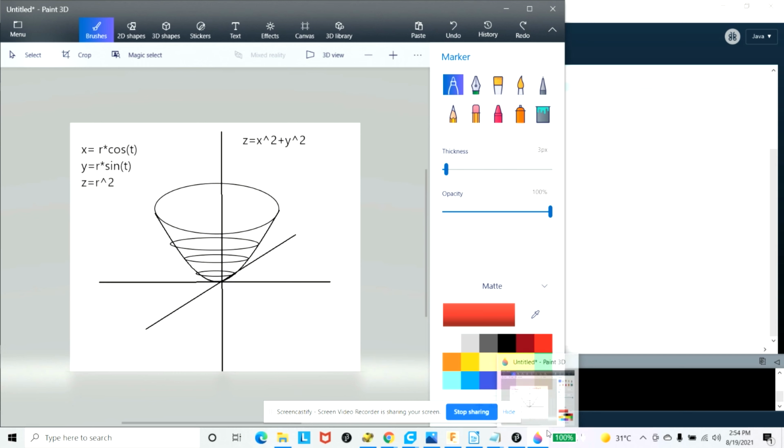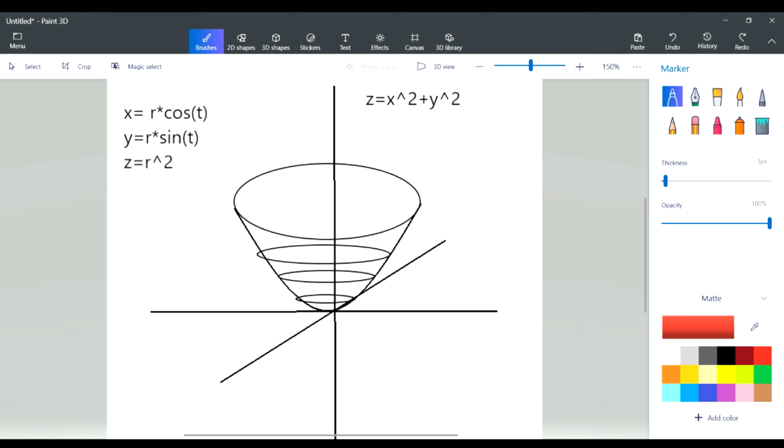And I know there are a million ways to do this, but here we'll do it by generating an STL file directly. Using whatever programming language you prefer, we're going to create and fill a text file with the triangles and do it in proper STL format.